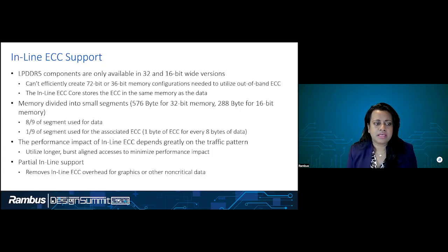In this case, since it's inline, 8/9 of the segment is used for the data, and then 1/9 of the segment is used for the ECC. And since you're using the same memory as the data for the ECC, you will see a little bit of a performance impact.